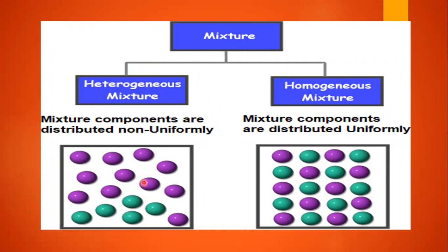That means we need to have fuel injection before the piston reaches TDC, so that when the piston reaches TDC there is complete mixing. Because of the high pressures developed by mixing of air and fuel, the self ignition temperature is reached in CI engines, and then combustion happens. Because of the mixtures, we have different types of combustion. If it is a homogeneous mixture, we have one type of combustion, and if it is a heterogeneous mixture, we have another type.